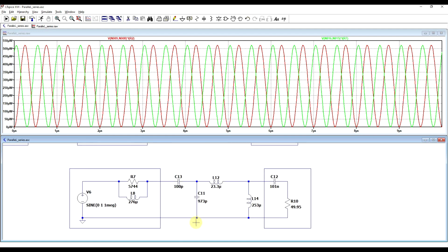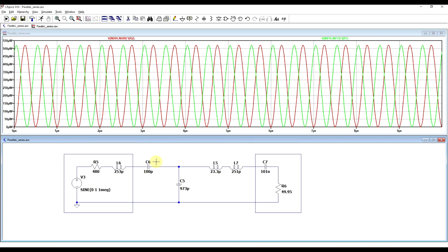But now, when we look into a bit more detail, having the two parallel elements in series with the signal source isn't that helpful, but having the two elements in series on the load side is helpful. So now we can start again from scratch with our matching network and provide a matching reactance to our initial signal source, and also provide a matching element to our equivalent load circuit. And this time, the two inductors can be united into a single component. Now we can see that we only need 200 something picohenry of inductance, so an extremely small value, but this wasn't necessarily obvious when we had the 100 picofarads there.